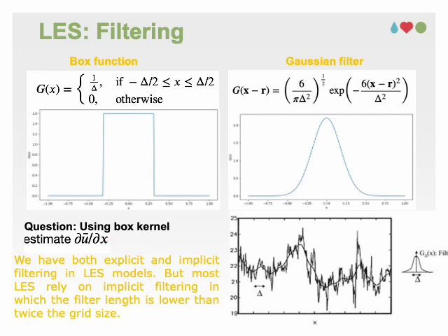Traditional LES models are based on implicit filtering, where the discretization operators and computational grid act as an implicit filter for the Navier-Stokes equations. These models do not require the application of any filter function. The explicit filtering approach uses an explicit filter function and is capable of minimizing the impact of discretization errors in finite difference code.